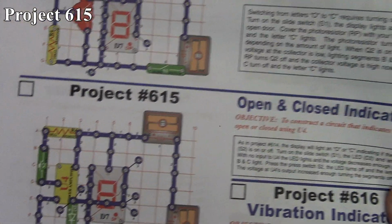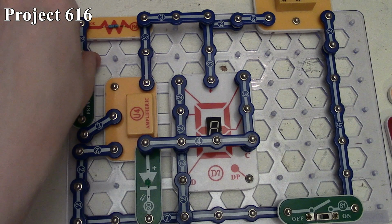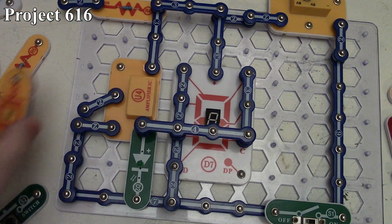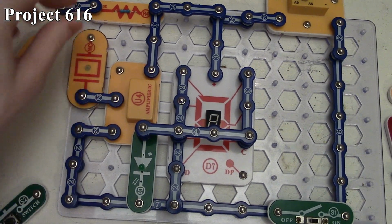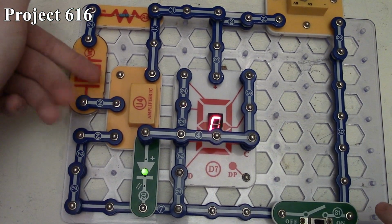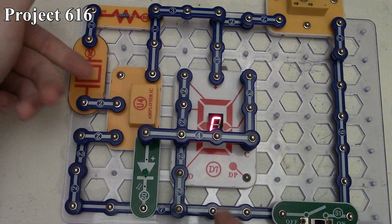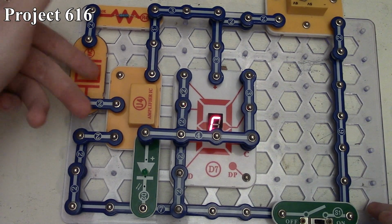Now project 616 is the vibration indicator, and for that we're going to take our press switch away and replace it with the whistle chip. And by doing that, we'll use the whistle chip as sort of a switch by tapping on it to change the signal on our amplifier IC. So as we tap the whistle chip, our green LED lights, and we also change the output segments on our 7-segment LED there.